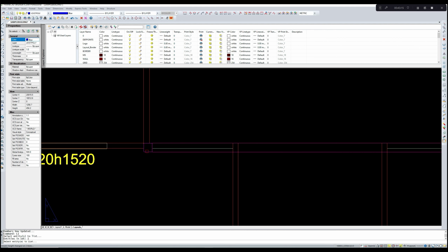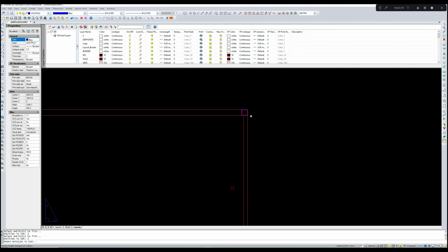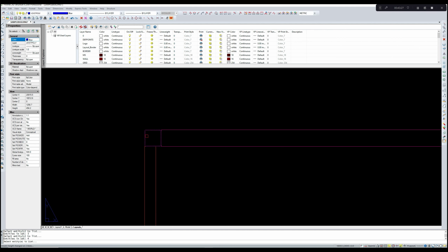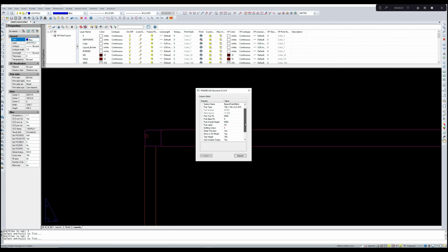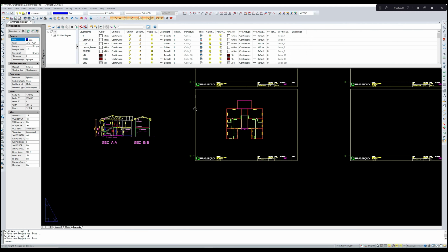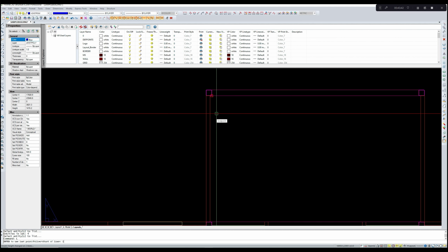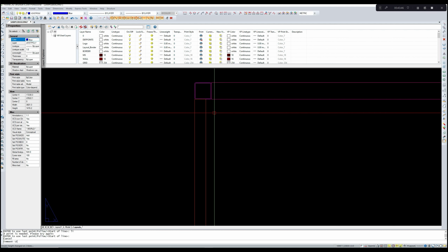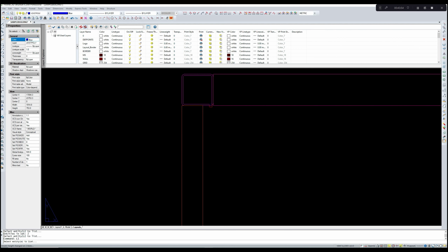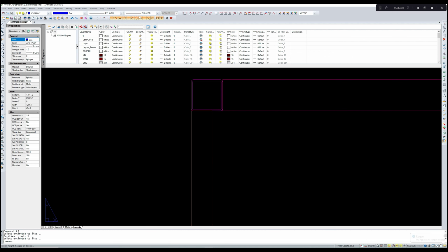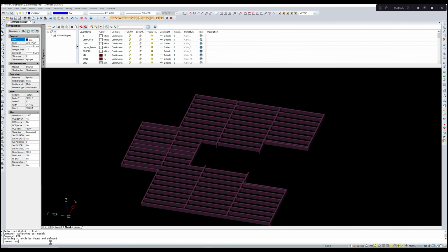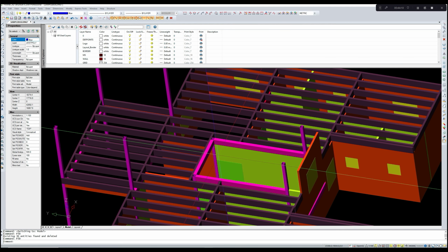List these items. LI command, then select these items. List them. Now the post overall height of 6500 has already been taken. So this is our 6550. LI. Let us go to 3D model, P3D and P3D, enter again. So our columns are properly set.